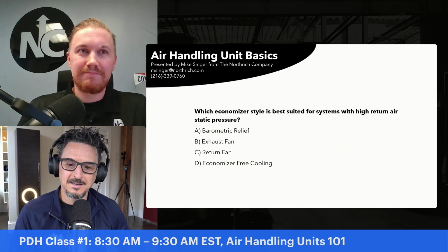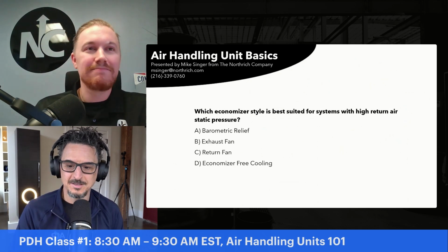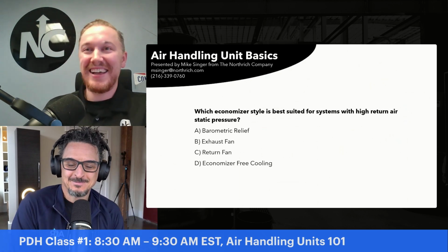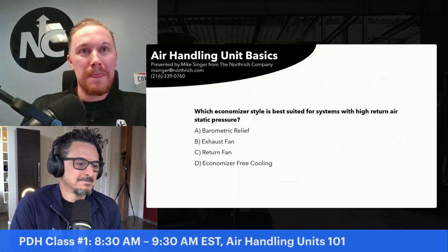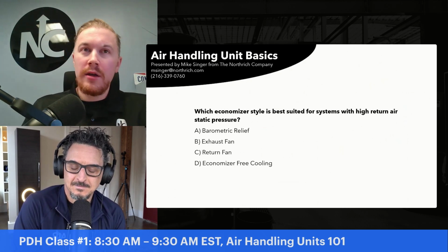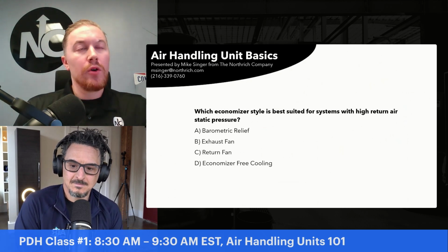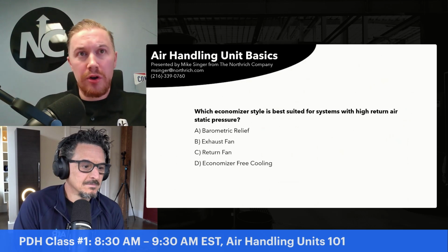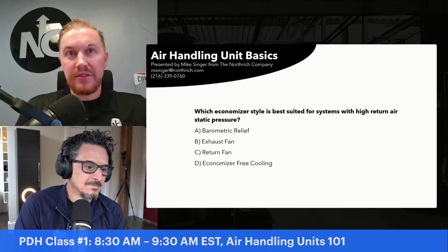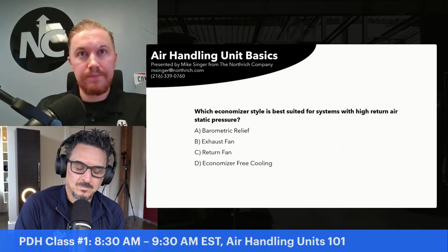We're getting a ton of answers. A lot of engagement in the chat, by the way. Mike can't see the chat, that's why I'm telling him. All right, our answer here is going to be that return fan. Whenever we have a drop over 1 inch of return pathway pressure drop, look at that return fan economizer as your number one choice.